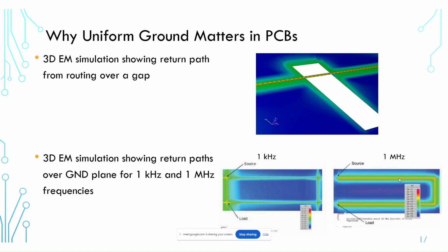Now, it doesn't matter for this signal, but what about signals on other layers that might couple to this same ground plane? Well, of course, same thing. If I were to, let's say, cut out some ground here, it's not going to do anything to the return current for the 1 megahertz signal, but it will create this situation if I cut out some ground and then try and route below this 1 megahertz signal. You would then get back to this same situation where you now have a big antenna that is possibly creating a situation that causes radiated emissions testing failure.